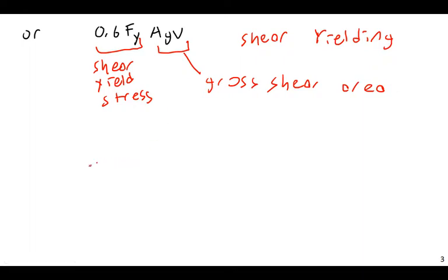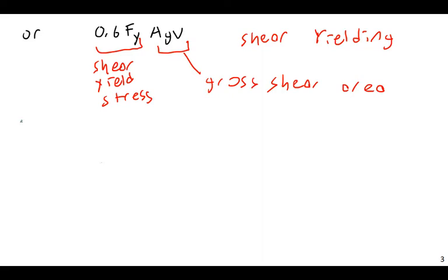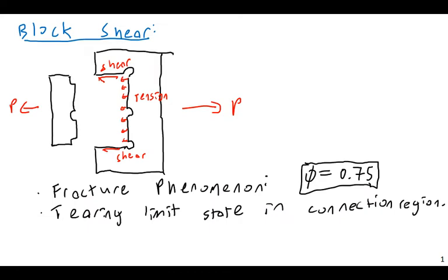And then we've looked at in shear, we have to consider both the fracture and the yield. However, for tension, we won't be considering simply a yielding. We're going to only be looking at a fracture case, because on the shear plane you can get either fracture or yielding, but on the tension plane it has to be fracture, because if we look at this plane here, this can stretch a lot on this plane. We can get stretching of this member here in shear, but on the tension, the only way this is going to fail is in fracture.